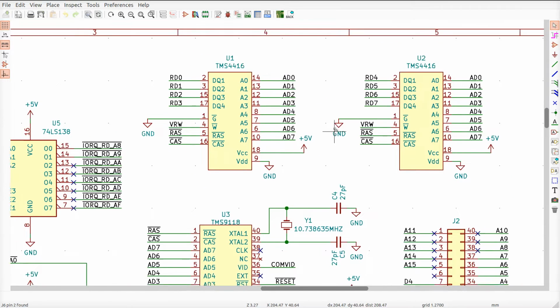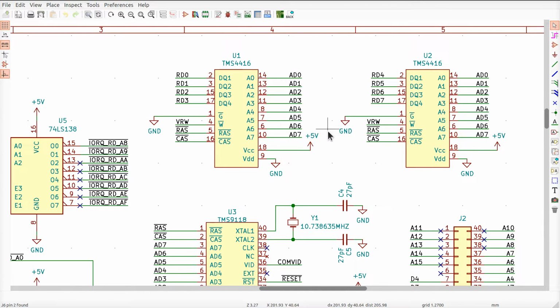Now, these DRAMs are, it's not clear whether I want to have the backwards numbering that TI loves to do on the address bus or not. This would probably matter if it was any other DRAM chip, or if it used a burst page mode data transfer.